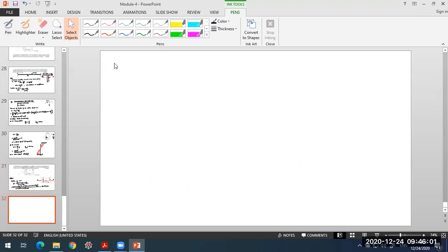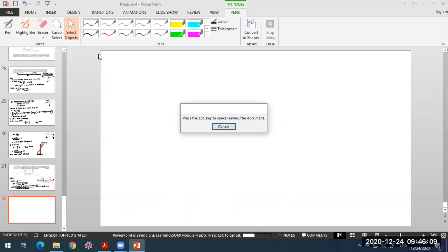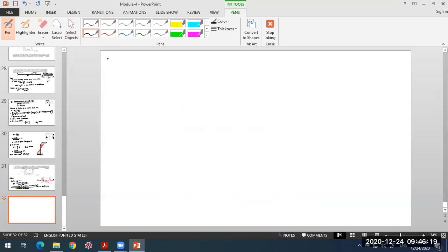Now after we have done that, next is moment of inertia of the section. So again go for applying the parallel axis theorem to determine the moment of inertia over the neutral axis or the central axis. Both are same in our case. So here moment of inertia of that channel section, actually it is a channel section here, what is shown to us.